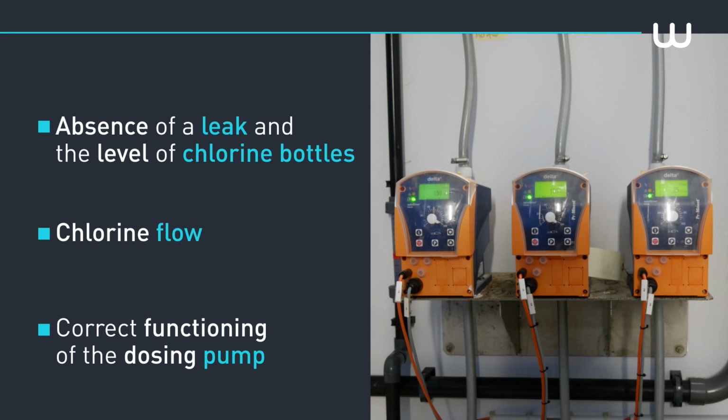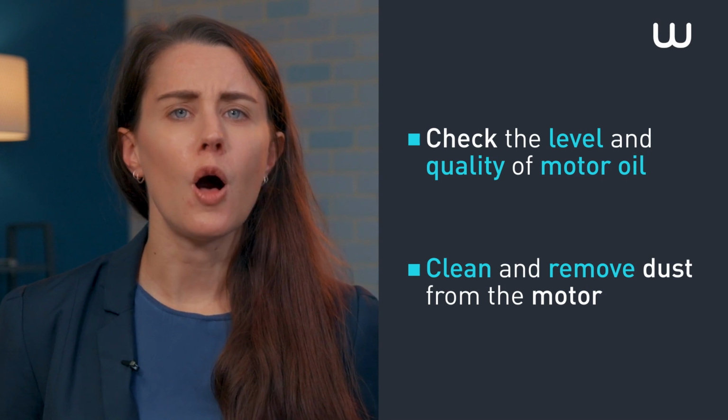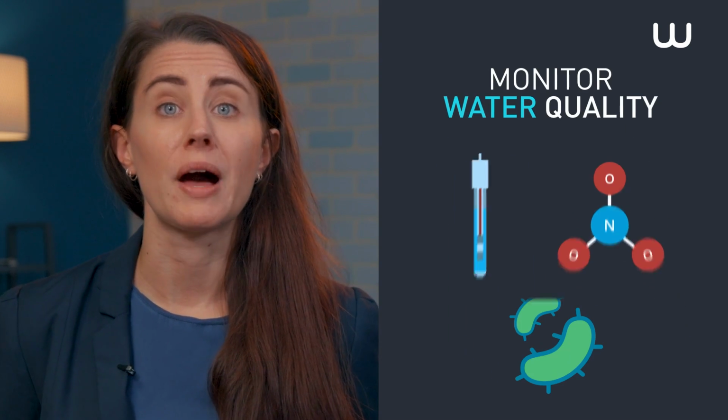It is necessary to regularly check that the membrane is not clogged, to regularly clean the dosing module, the suction valve, the delivery valve, and the dosing head, to check the level and the quality of motor oil, and lastly, to clean and remove dust from the motor. It is also necessary to monitor water quality. In other words, to check various physical, chemical, and microbiological parameters. Let's now look at some examples of preventive maintenance at wastewater plants.